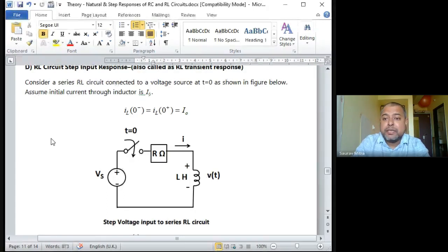The last experiment number 2, the last code I am telling you, is mainly to make you understand what sampling is and what the effect of sampling frequency is. I don't remember exactly, but I think I had taken a 100 hertz signal, and then I took different sampling frequencies and kept showing you, for example, if the sampling frequency is 200 hertz. Sampling says that your sampling frequency should be twice that of the baseband signal. Baseband signal means the signal you want to digitize, the signal you want to convert into digital.